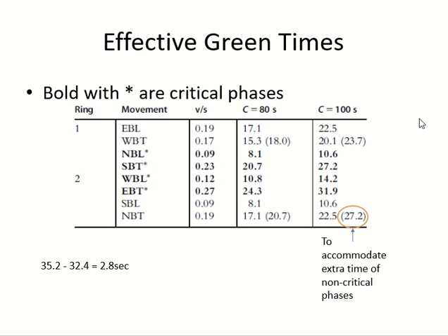Okay, so according to this, what will happen? This will remain open for 20 seconds and they should close in 17 seconds. I cannot do this. I made them parallel. So this one should also close in 20.7. Got it? Okay, so after you calculated the green time using that equation, then you have to see which